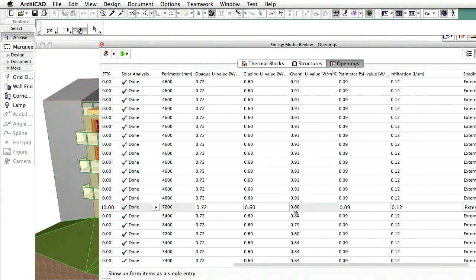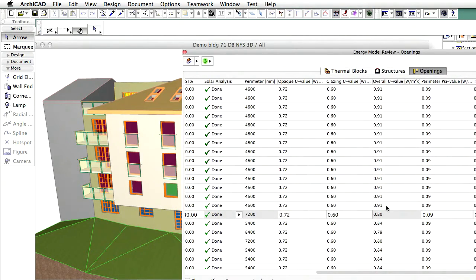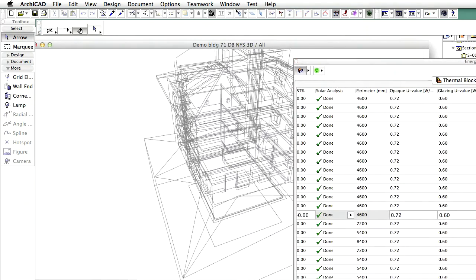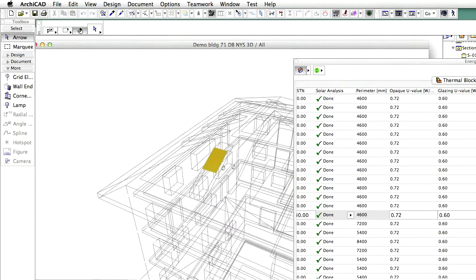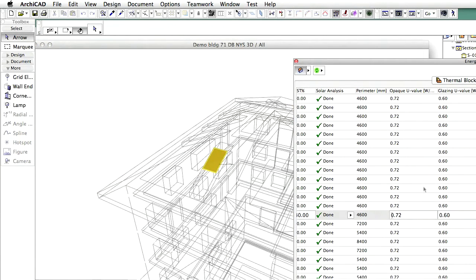The overall U value for a balcony door, for instance, is slightly different from the overall U value of a window because their glazed area to frame area ratio is also different. Naturally, the infiltration around the advanced window's perimeter is also reduced to reflect the differences in applied technology for the installation of the more expensive high-performance windows and glazed doors.